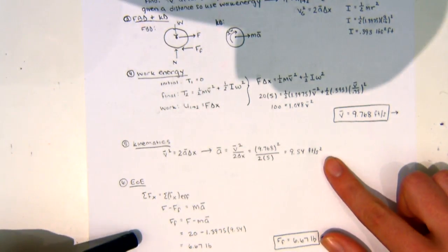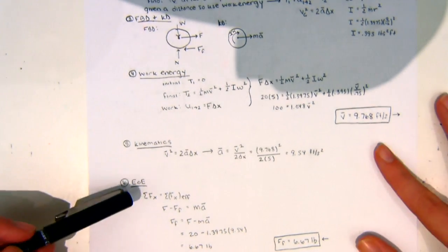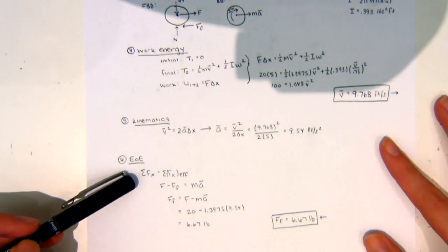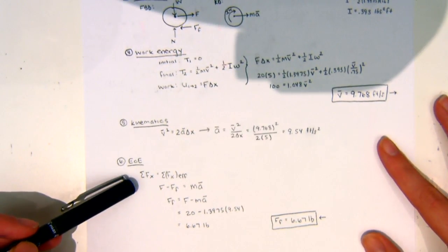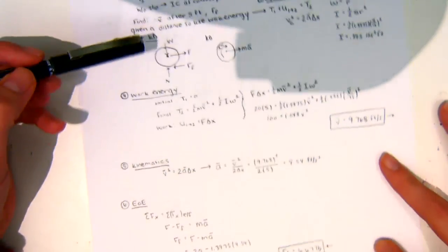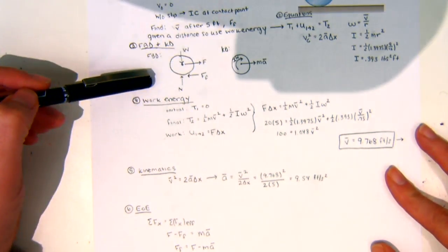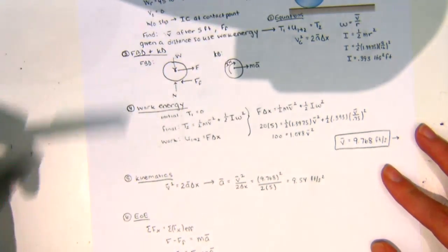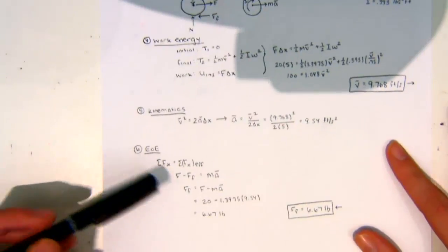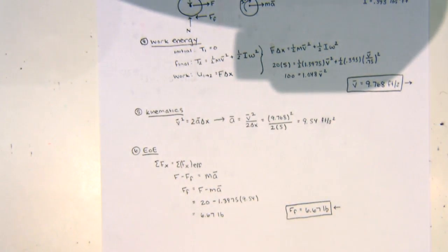Then from there you can go back and do what you did in chapter 16 and equate the sum of forces of the free body diagram to the sum of forces on your kinetic diagram. So essentially you would just have the force that's pulling it, which is 20, minus the force of friction is going to equal mass times acceleration. Well, you found the acceleration, you know the force, and that's how you get the frictional force for it. So that one wasn't too bad. I think that's pretty straightforward.